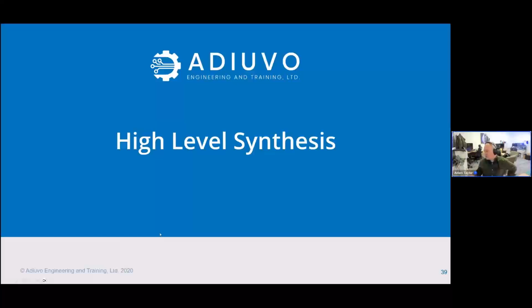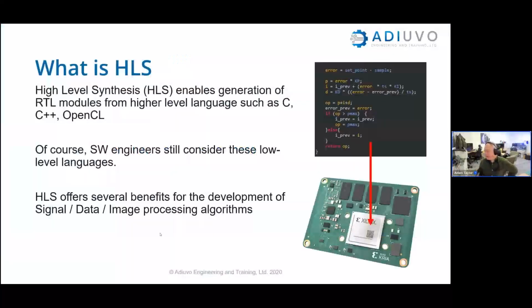So one of the tools that we can leverage is Vitis HLS, and that allows us to take our untimed C and move that into timed RTL, either VHDL or Verilog in this instance, because that's what dropped out. It's not very good for the control plane, but for the signal generating, data processing plane, it's really powerful.